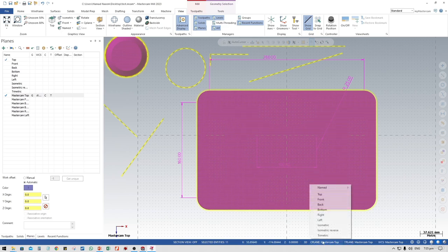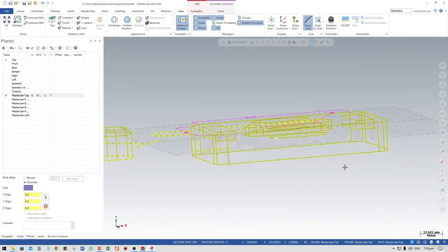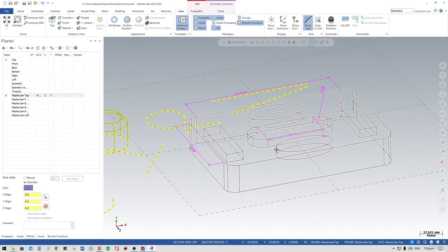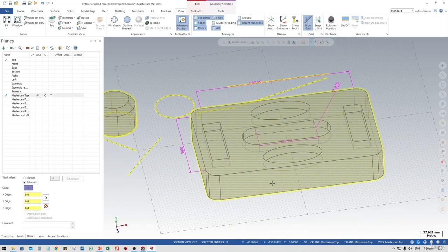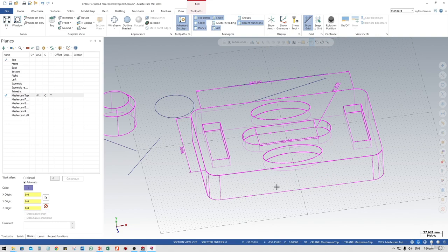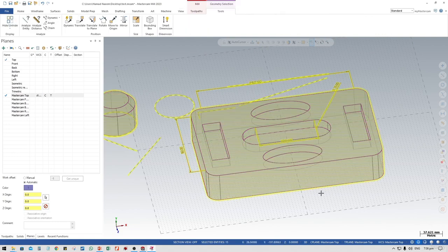Over here you will see that you have the selected construction plane, the tool plane, T for tool plane, and WCS, which stands for work coordinate system. With that, you have some different views, like the wireframe view, which will convert all 3D parts into wireframe. And there is dimmed wireframe, where you'll see your wireframe and solid part also, but in a dimmed form. Okay, put it more clearly by selecting it.